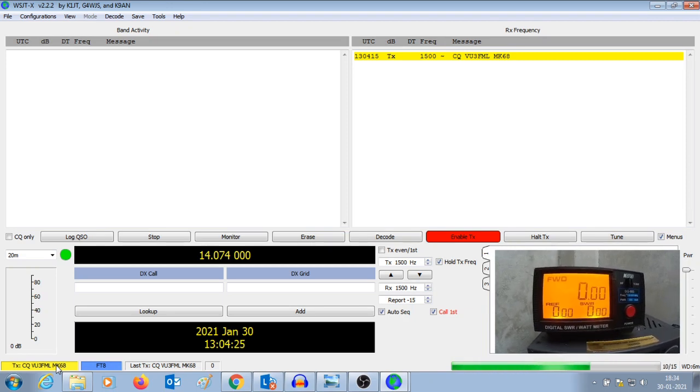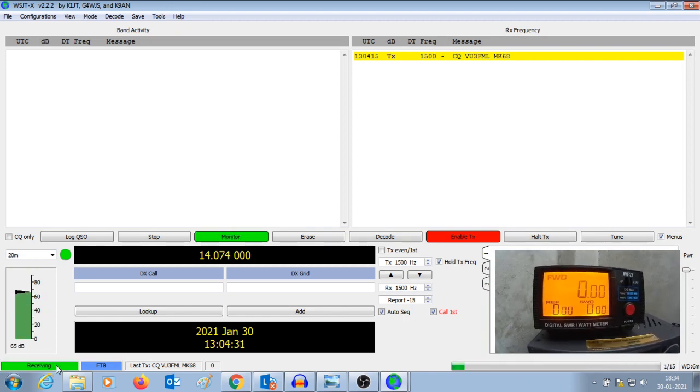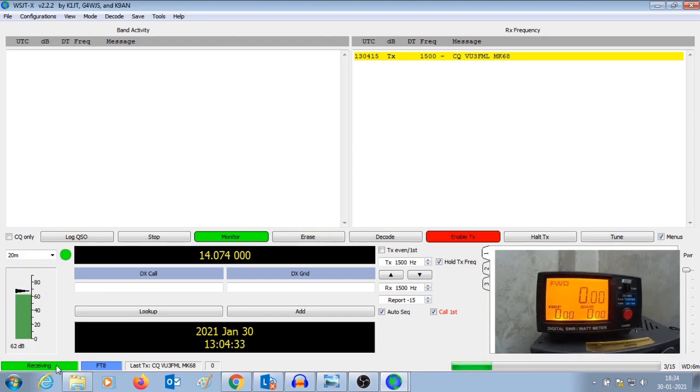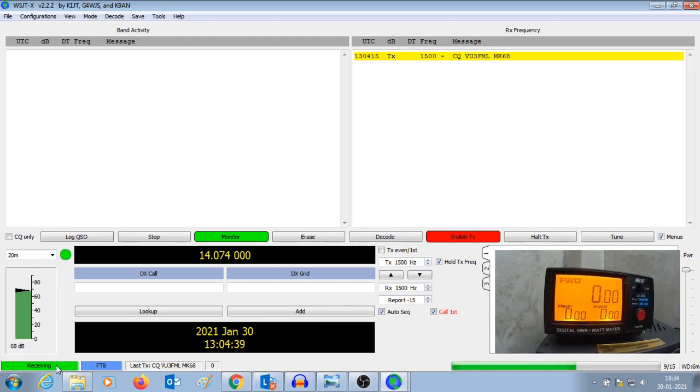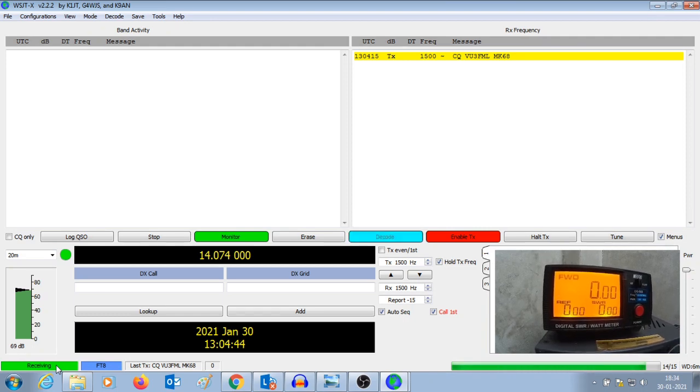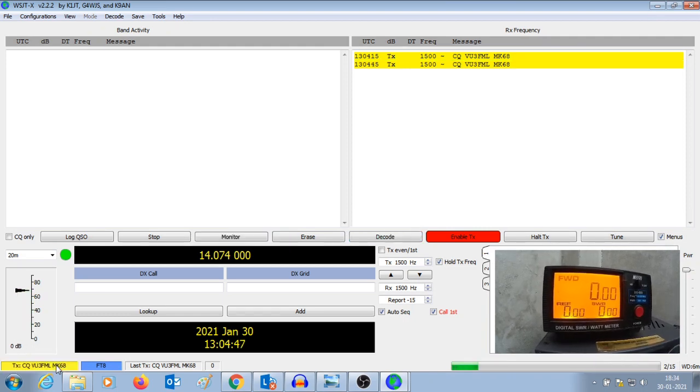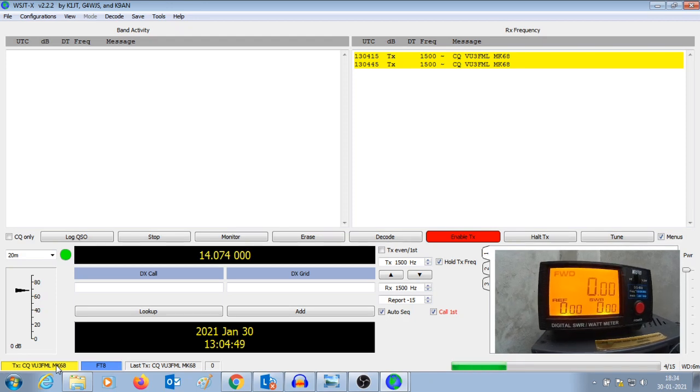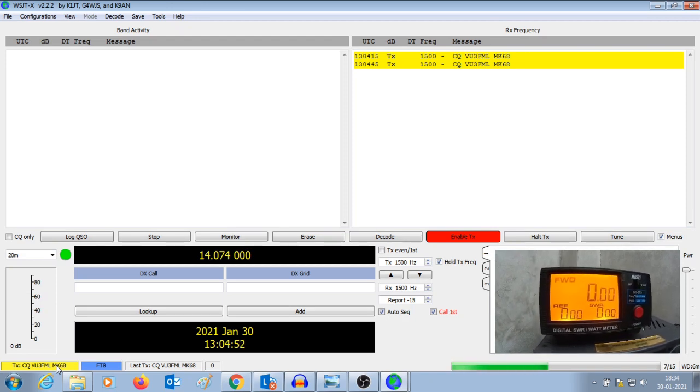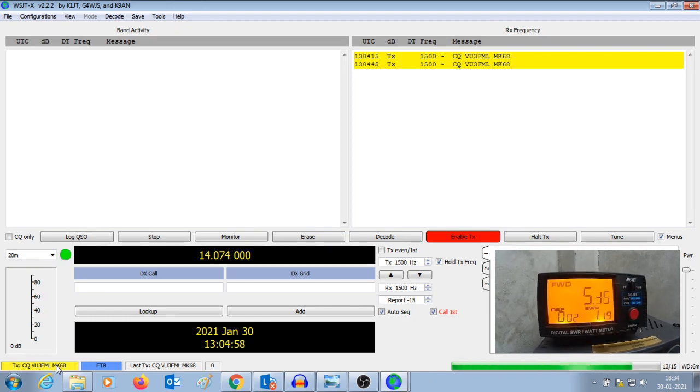This is because the circuit is at the least sensitive setting. Now I will increase the sensitivity by turning the knob clockwise, and then you will see the PTT being triggered. Okay, now WSJT-X has gone into the TX mode, but there is no forward power. Now I'm going to just rotate it, and there it goes. This is the level where it got triggered. So this is the sensitivity functionality of the interface.